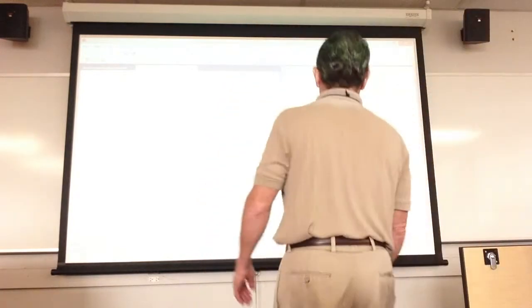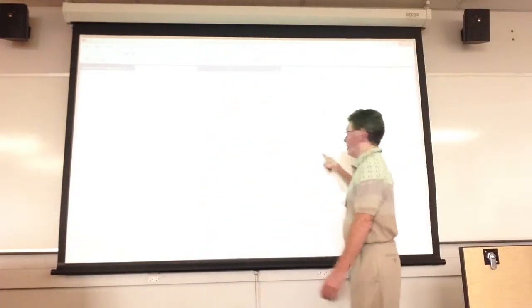We set up port C to be an output. We've written something to it. Then we set up port C to be an input. And then we just read from it into R16. So all I'm doing is setting up some test data because I don't have it in hardware. I need to do something in port C. All right? So the contents of port C have now been read into R16.